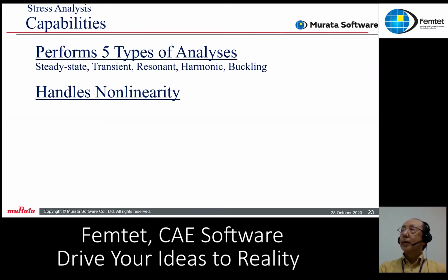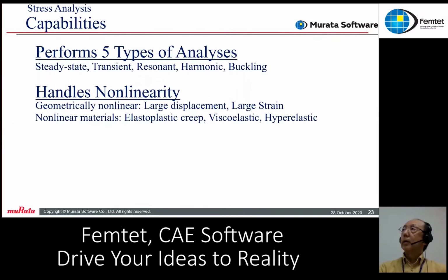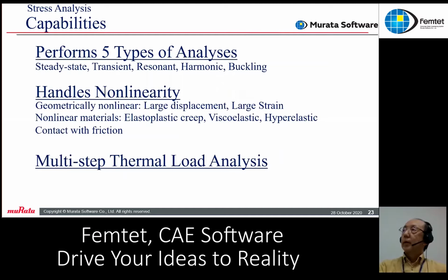And it handles nonlinearity: geometrically nonlinear, large displacement and large strain. Nonlinear materials, that is elastoplastic, creep, viscoelastic, and hyperelastic. It also handles contact with friction. And it is capable of multi-step thermal load analysis. And birth and death are taken into account.